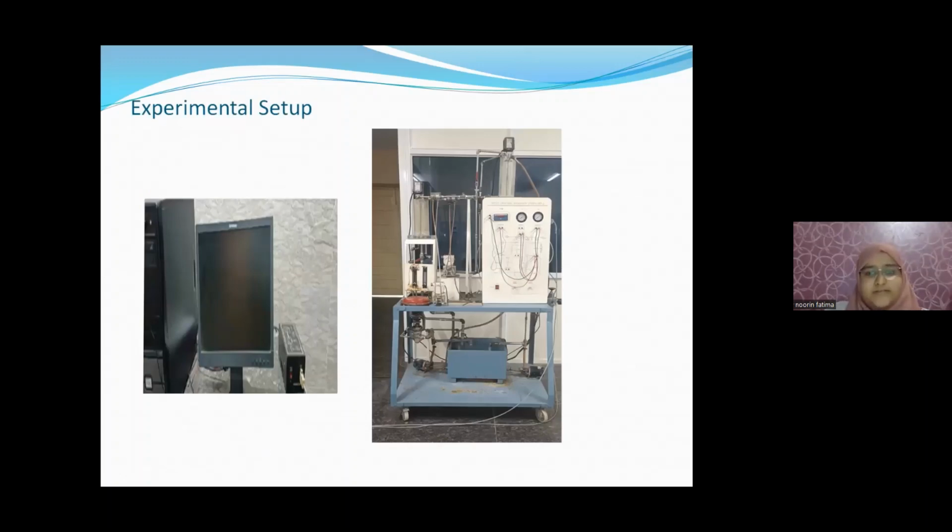This is the basic setup we had in our lab. Here, this is the reservoir. This is the overhead tank. This is the process tank or second tank in which the level was controlled. These are the pressure indicators. This was the level indicator. This line was the level transmitter. And this is the computer which is connected to the equipment. The equipment was maintained at a pressure of 12 to 15 psi.